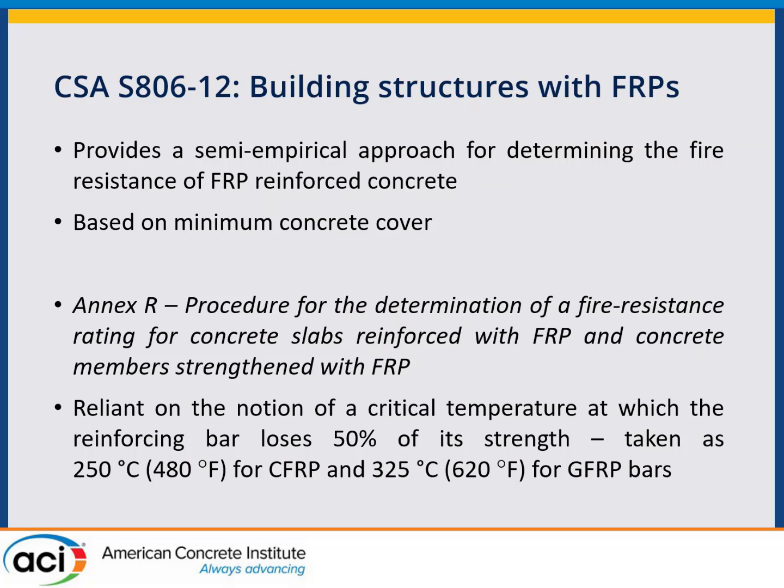In Canada we have CSA S806, which is for building structures with fiber reinforced polymers. There is a semi-empirical approach for the fire resistance. It is based upon the minimum concrete cover, but unfortunately it's still using this idea of the strength of the FRP as the approach.